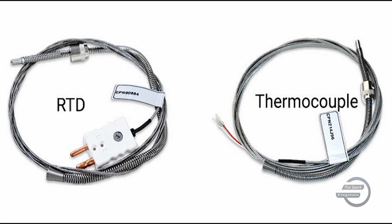So, where the temperature range is up to 200 degrees Celsius, the RTD type sensors are used because these are far more economical as compared to thermocouples. But in case of temperature above 200 degrees, then we have to go for the thermocouple sensors.